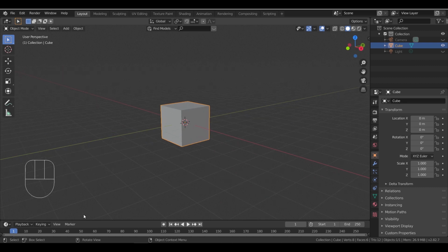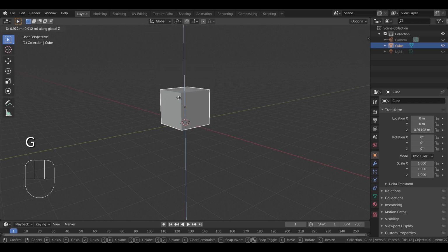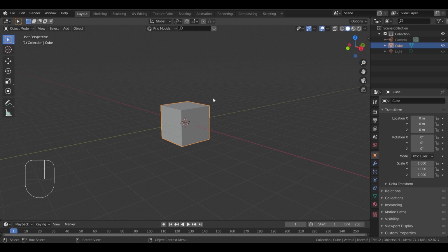In this bottom left area, I have for you the shortcuts that we will type, and you need to know them because selecting the tools and then using them will take ages, and you have to be up to speed in the arch field. So, pressing G is the same as selecting the move tool. Pressing Tab will make you go into edit mode.